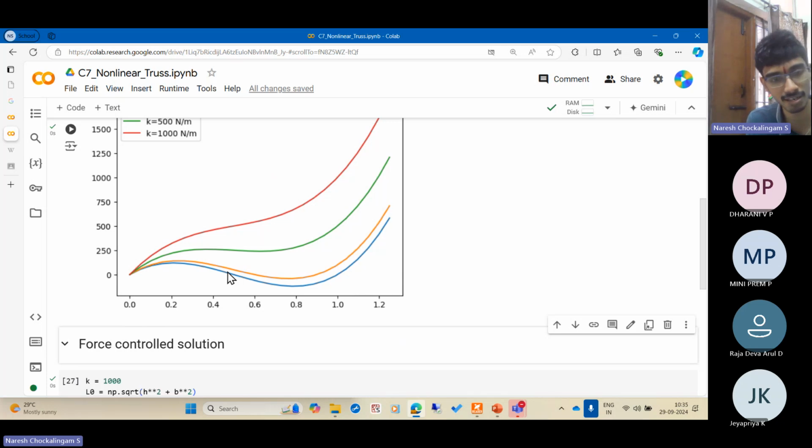It will cause the specimen to explosively fracture. Instead, if we control the displacement, we can get it. Or if you have a material which doesn't have an ultimate load, then you can increase the force under your control. There's no problem. The material will respond very well. So for the moment, I'll avoid this orange curve and look at the red curve.